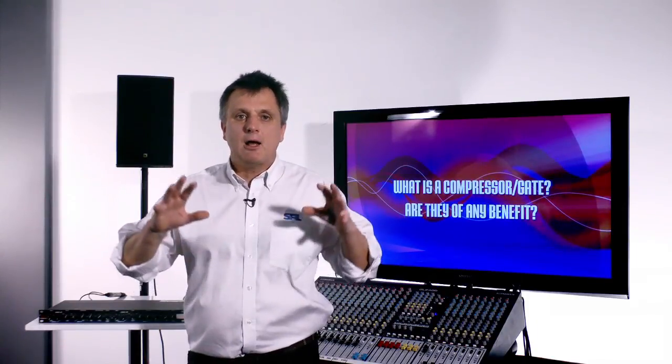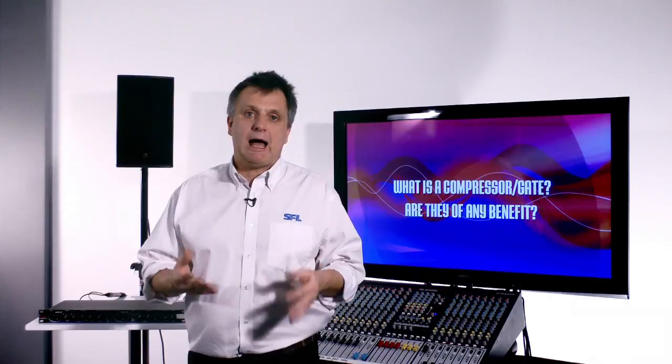Please do be aware that the most common place to insert a compressor is right at the beginning of the signal path. This does mean that the feed to the monitors, although they are pre-fade and not affected by the position of the fader, are, however, affected by the position of the compressor. A musician who has their personal foldback being compressed is generally not a happy musician. The general approach, therefore, if you are mixing monitors from the front of house desk, is that you need to be very careful with the amount of compression that you add. Maybe 6 dB gain reduction at a maximum.